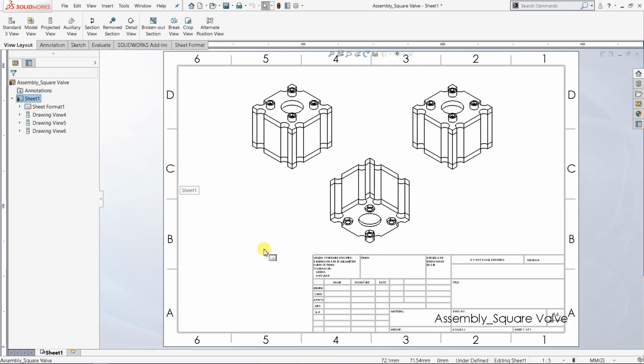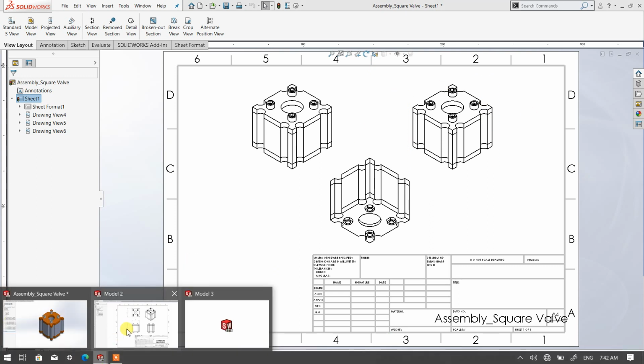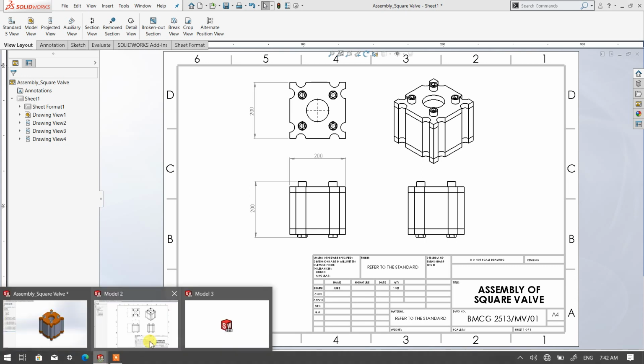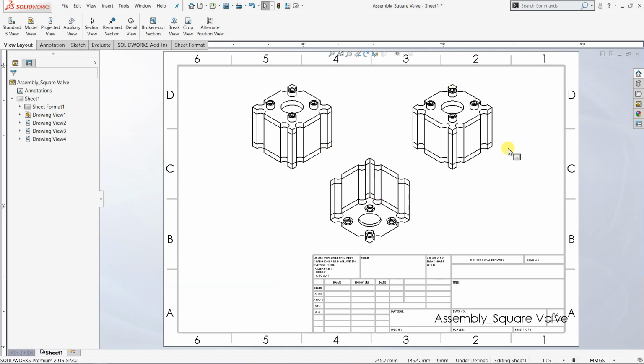So it means that for the assembly drawing, especially when you would like to create the 2D technical engineering drawing in your project later, you need to have two types of assembly 2D technical drawing, which is this one, and also this one, like this. Okay, guys, so one together with the orthographic view, and another one which only involves the isometric view. A few isometric views, as you can see over here.